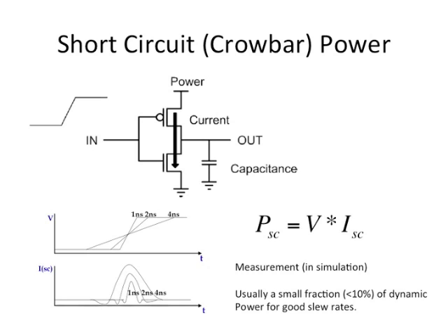So what we normally do is ignore the short circuit power, in the sense that you reduce it by making sure you have good sizing and good ramp rates which are not too slow, and small sizes. If I make a gate which is bigger, of course I'll have more short circuit current.